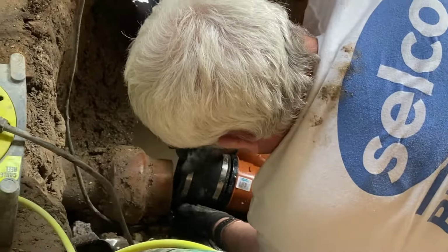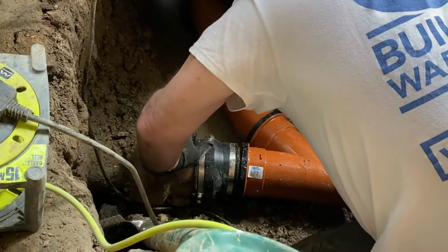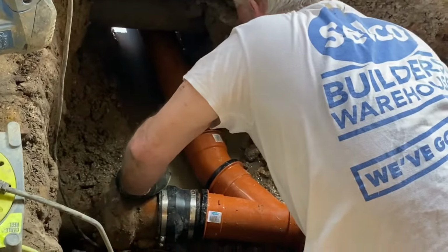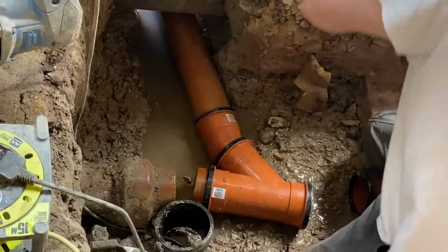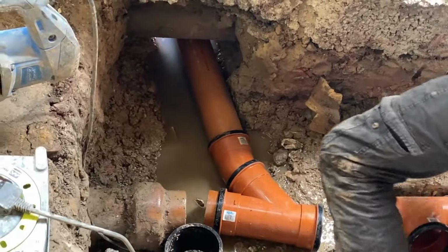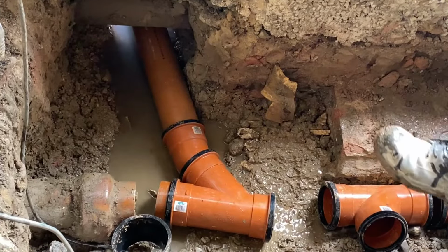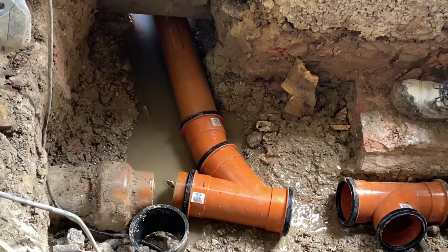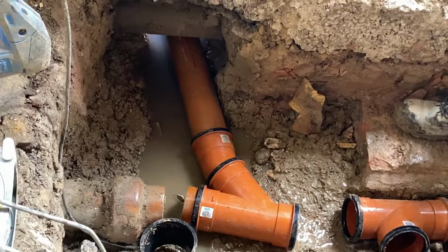So it's really now a case of connecting that access rodding section, which is what's going into the garden, which is where that long pipe is being laid now, and then connecting the parts together. So you can see here we've got a slight angle, so it's a nice bend going into the sewer pipe. And the reason for that is obviously when you're putting your rodding access in, you need it to be able to go into that pipe and also to be able to be pulled back out again.